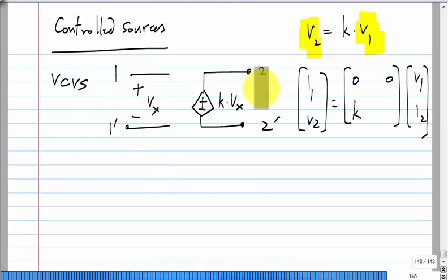You basically open circuit this and then you find the resistance looking back to this side. So, that will be 0. And in fact, you can try to measure any of the other parameters y, z or h. What will happen? At least one of the parameters will come out to be infinity.